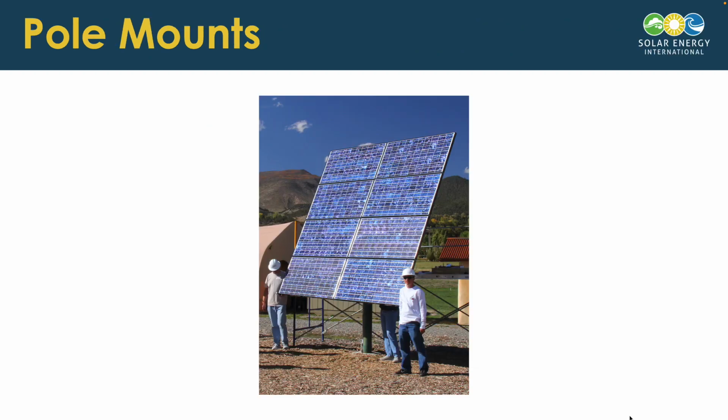We also have, or we could build pole mounts. Pole mounts usually means we have a center pole, usually a singular pole, and that is going to be set in a big concrete block. And then we can build small to mid-size solar arrays on that. Pole mounts have a better tilt adjustability, allow some versatility, and often some more height for the array if that's something that's needed.